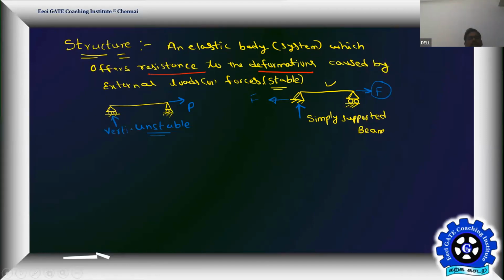It only gives the vertical reactions, but not the horizontal reactions. You understand that? Vertical reactions are only resisted by the roller. Please understand that. It is only the vertical reaction that is being taken by the roller, but not the horizontal. But this is the hinge support, and the hinge support has the ability to resist both the horizontal as well as the vertical forces. That's why it is.